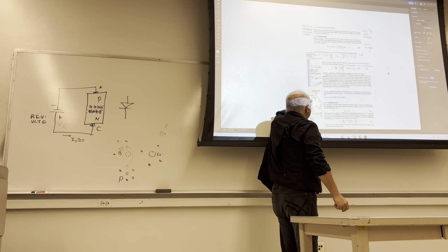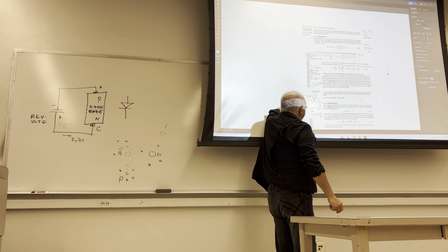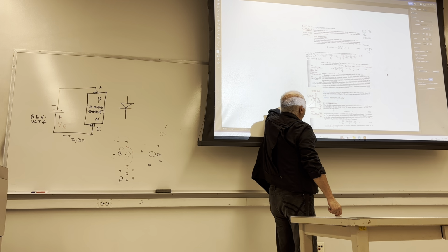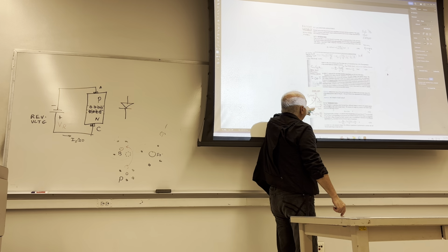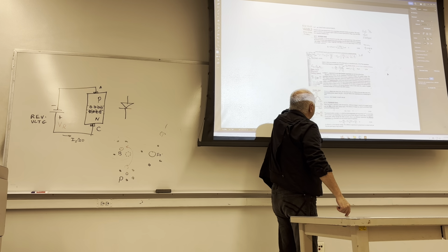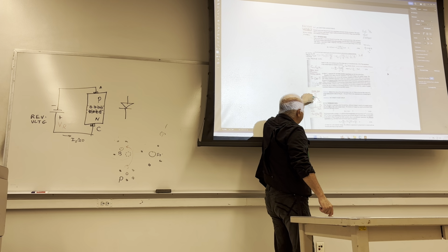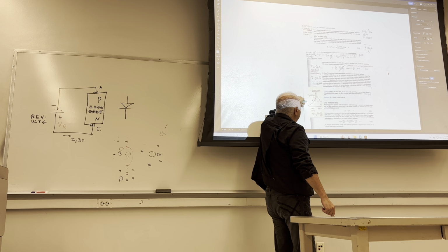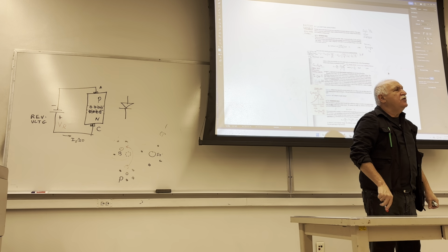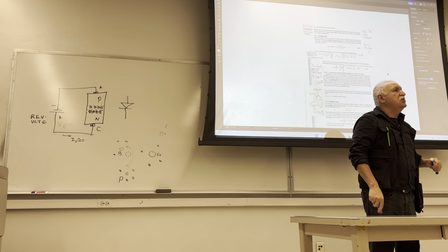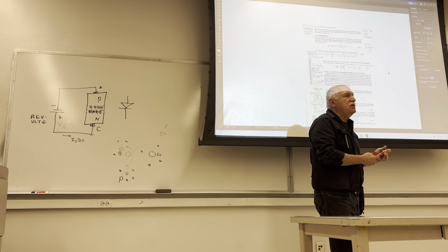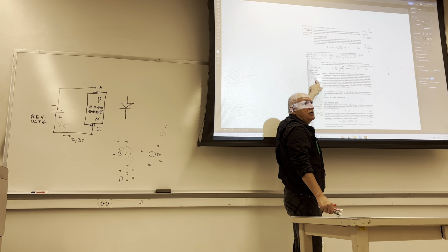It is known as junction capacitance, reverse junction capacitance, and it will be inversely proportional to the radical of applied voltage. So if you start reversing the voltage and increasing, the capacitance will keep dropping with that profile. This is known as the reverse voltage variable capacitance diode. They call them variable capacitance diode. A special symbol is used.